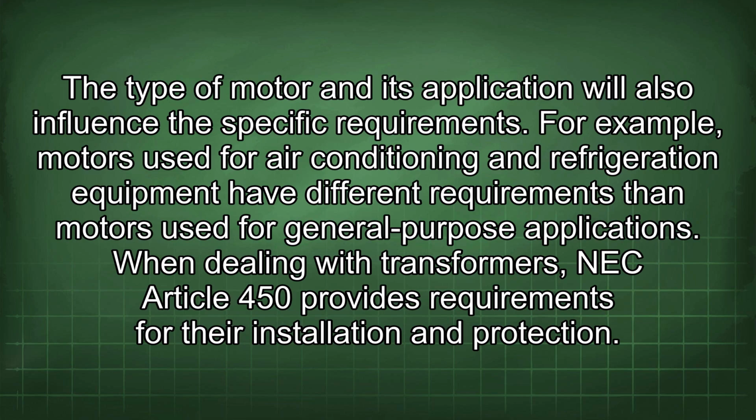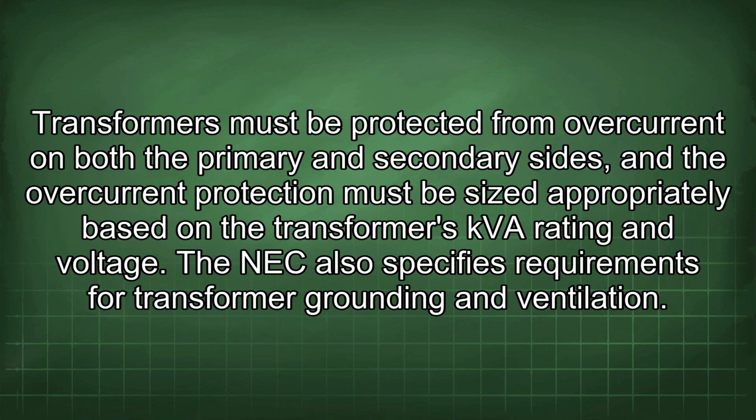When dealing with transformers, NEC Article 450 provides requirements for their installation and protection. Transformers must be protected from overcurrent on both the primary and secondary sides, and the overcurrent protection must be sized appropriately based on the transformer's kVA rating and voltage. The NEC also specifies requirements for transformer grounding and ventilation.